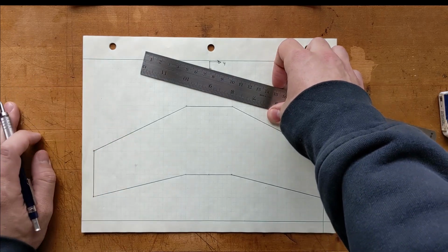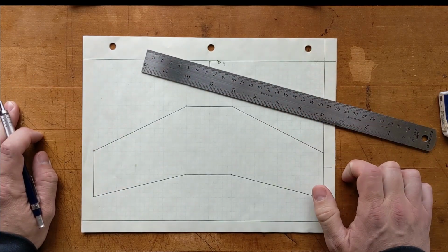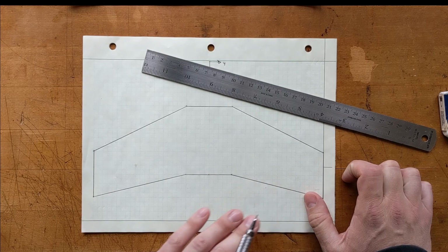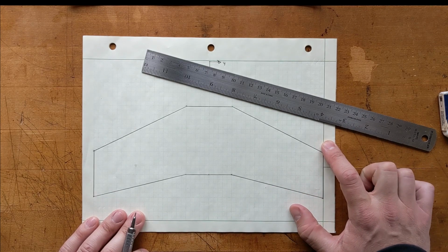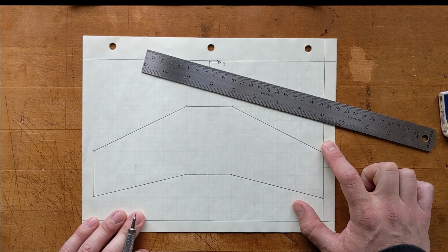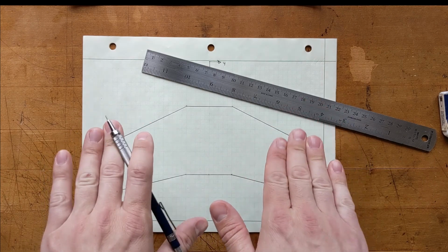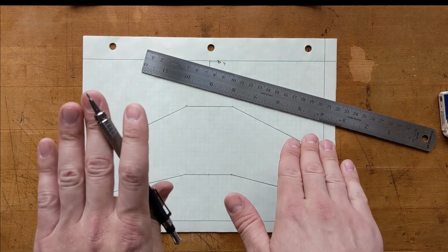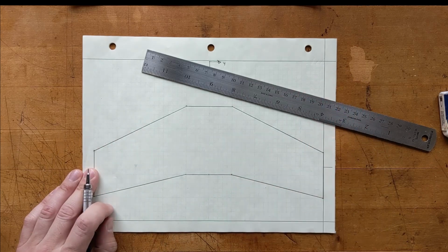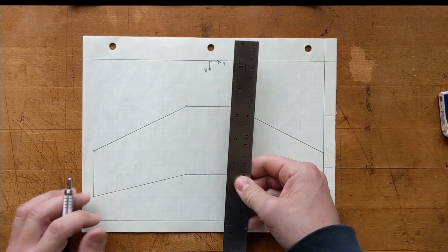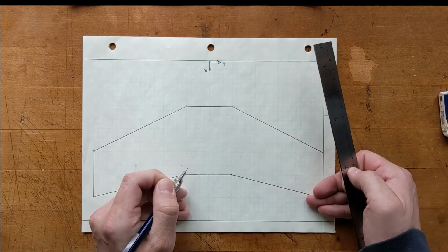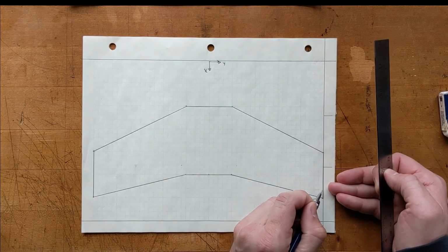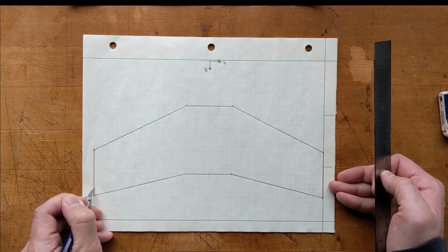Now, for a flying wing, it has 2 control surfaces, one on each trailing edge. These function both as an elevator when they both move up or down together, and they work as ailerons when they move opposite each other. So let's just put on some notional elevons, as they're called.